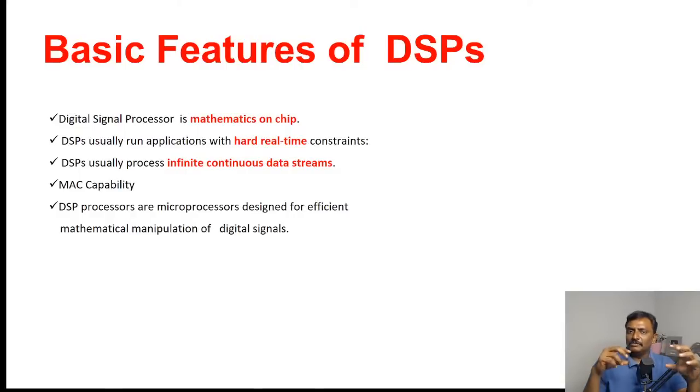Whereas with a microcontroller, if you want to implement simple applications like a simple door lock, then you could go for a microcontroller. But there are some microcontrollers which also have a DSP engine on them, like the Cortex M4; the ARM7 has a simple DSP port, where it could process simple algorithms. But the DSP processor is meant for audio and video applications where you have complex mathematics involved.